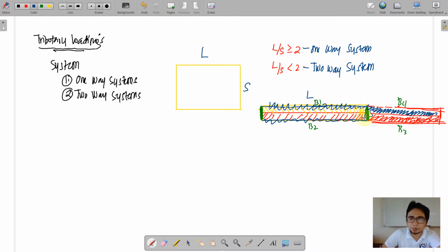As we can see, it will just tend to stiffen our framing system, the sub beam here or the transverse beam here. These beams would have a minimal carriage of the loading, and the loading again is distributed more on the longitudinal beams along the long direction, say B1 and B2, B3 and B4.